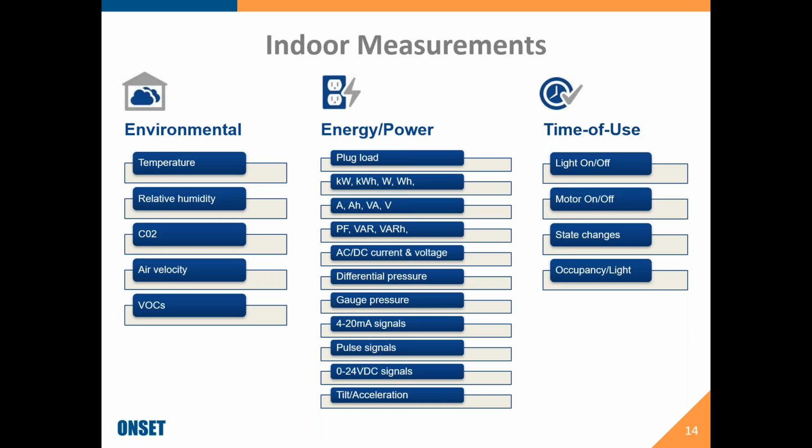Typically what happens is you're going to select a data logger based on, do you need USB historical data? Do you want some Bluetooth logging? Or do you want remote logging when you're in a different location from that? You're in a different city, and that would dictate the data logger and adding sensors that you want to measure.